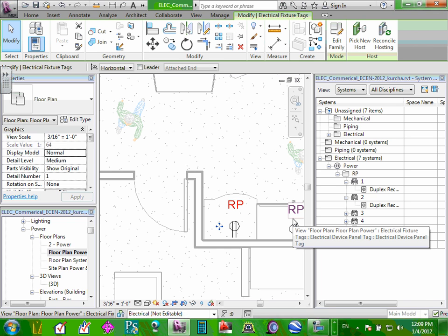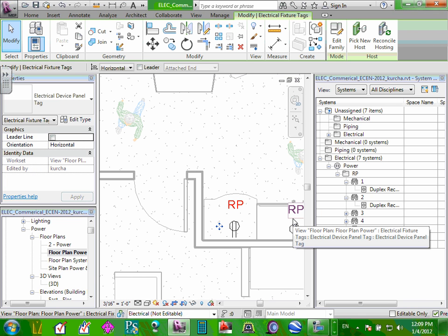The tag. And then I'm going to stop, guys. Can you guys see the tag here? Aladipo, can you see the tag that came immediately when I circuited? The receptacle had a tag. Now, this is not the tag I want. I need a tag that shows 2 things. For receptacles, you need a tag that shows the panel and the circuit number.